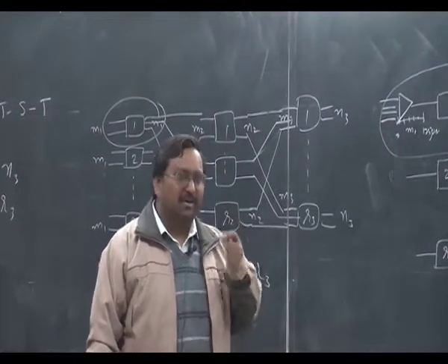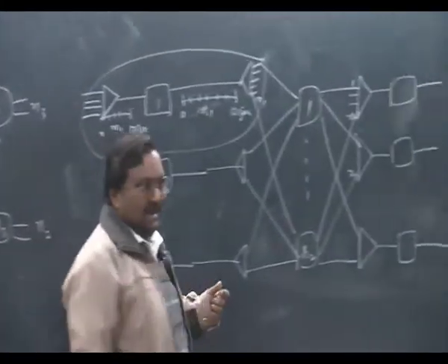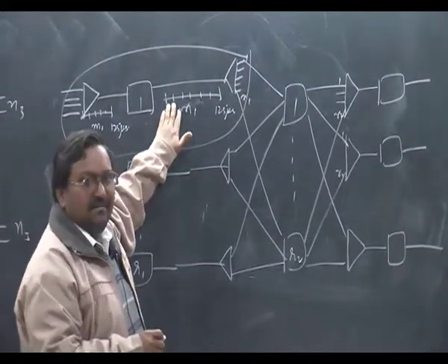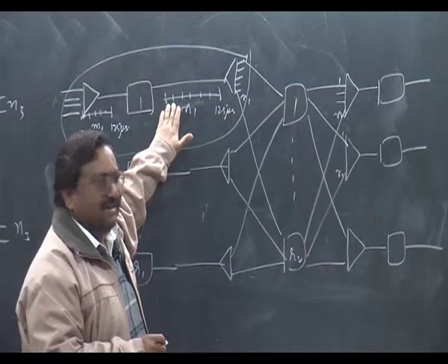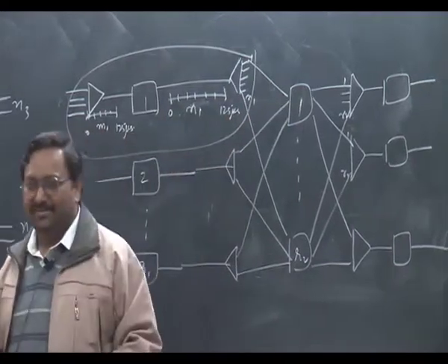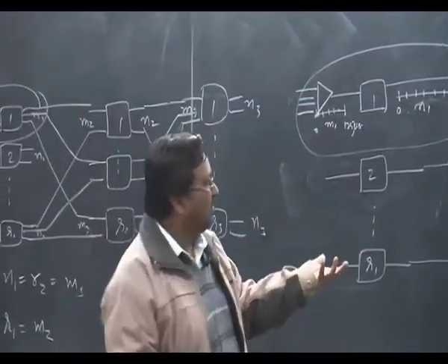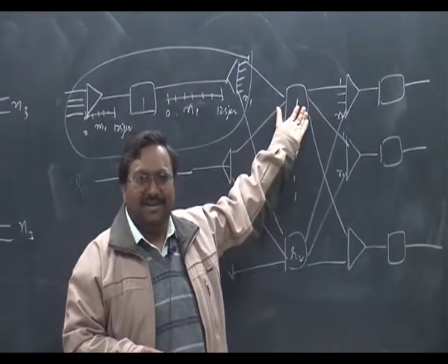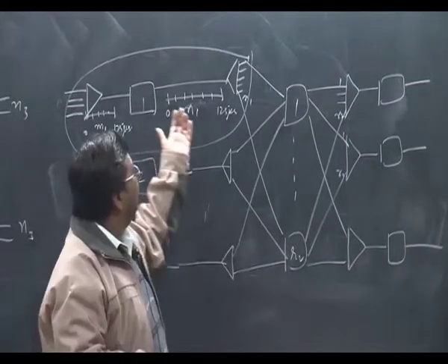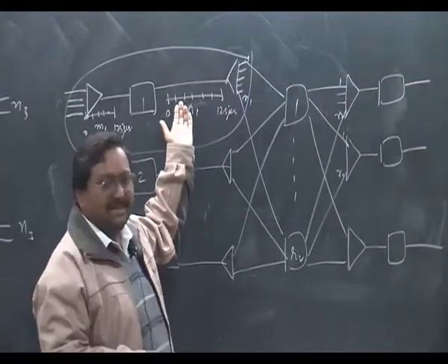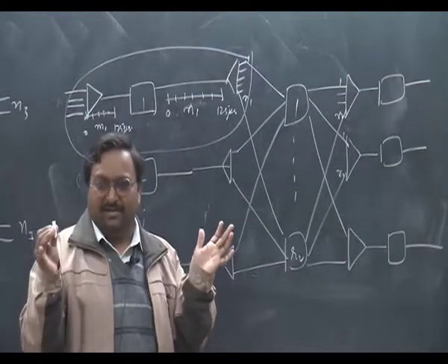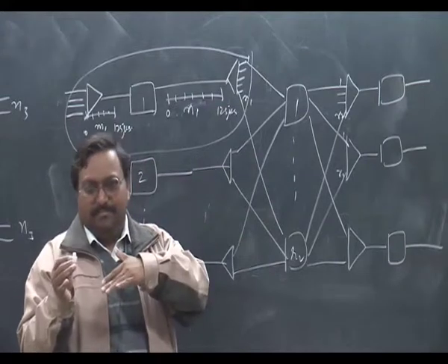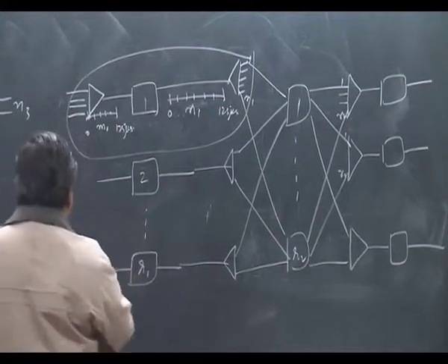Now, one important thing which you will notice: during the period when time slot number 1 is there, which one of the switches is in action? Are all the switches in action all the time? You tell me that. Only the first switch is operating. All others are silent because their output, the second output, will come only during the second period. I am not doing any time expansion in the demux. I simply split them, I have just used that pointer thing.